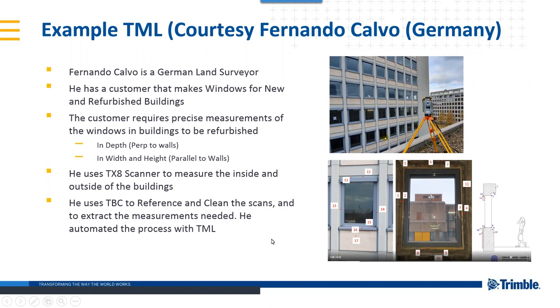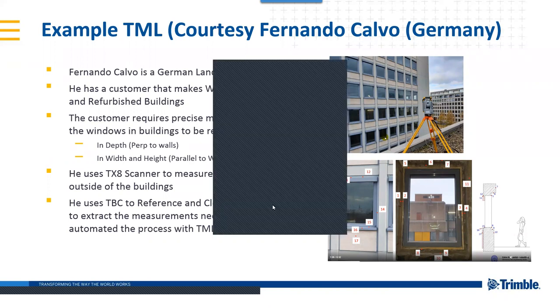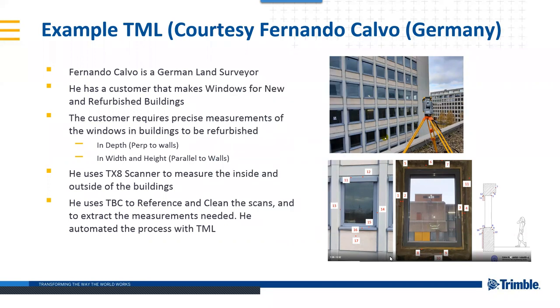And this is a great example of where the tools are all there in Business Center. We handle point clouds, we handle point cloud cutting planes, we handle measurement functions, we handle create point functions from the point cloud. But to do the right points in the right locations in the right sequence, to tag them correctly, and then to measure the distances and the elevation differences and all those kind of things is a little tricky. And to do that manually for every window, for hundreds of windows in a building, is an extremely time-consuming process. So Fernando wrote a dedicated routine to handle all that.